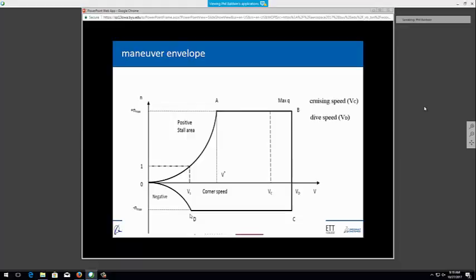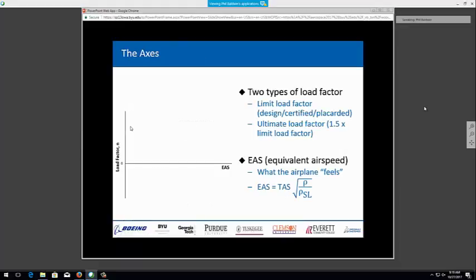So we won't go into these, but experimentally, with some analysis, load parameters have been defined so that we have some sort of gust load factor as a function of airspeed. It will be a linear function of airspeed. There's a number of these out there, ones that are specified by the FAA or by the European agencies also.